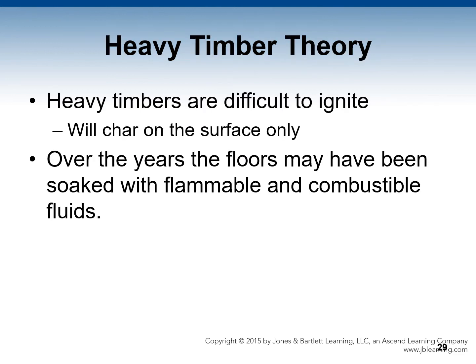Heavy timber theory means that heavy timbers are difficult to ignite and will char on the surface only. Yet, floors of most heavy timber structures are often soaked with a variety of flammable and combustible fluids over the years, altering ignition and combustion characteristics of the floor planks and beams.